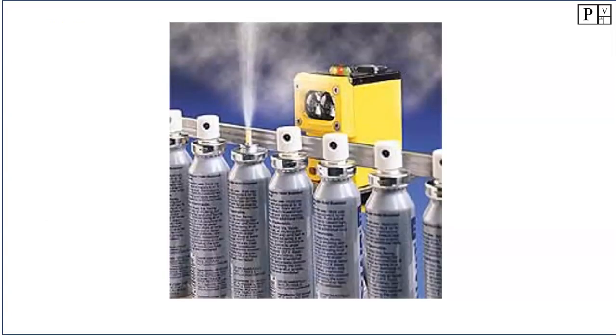Okay, let's take a look at this one. This one always trips people up. It looks like we have these perfume bottles going through, and the sprayer on the top of the unit has come off. This one doesn't seem to have a reflector. It's not looking for the presence of metal, and a capacitive sensor would have to be way closer to look at this. So this is a photoelectric sensor, and there is no receiver on the other side and no reflector that we can see. So this is a diffused sensor.